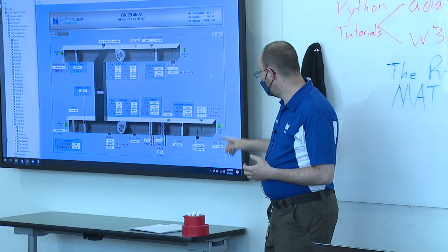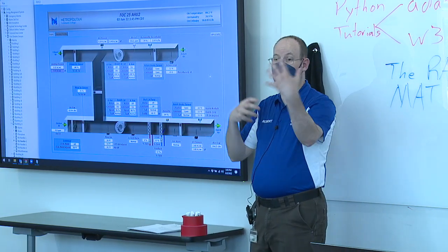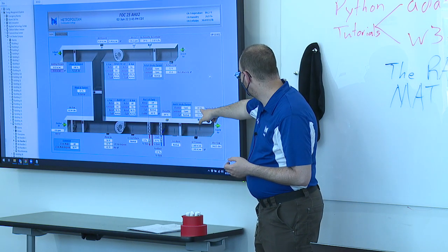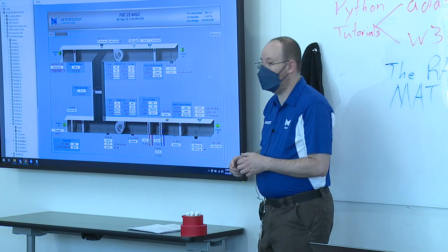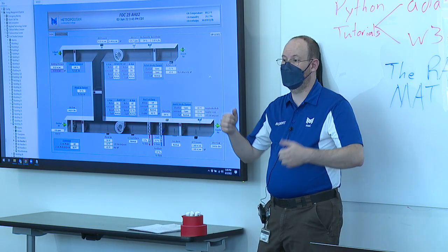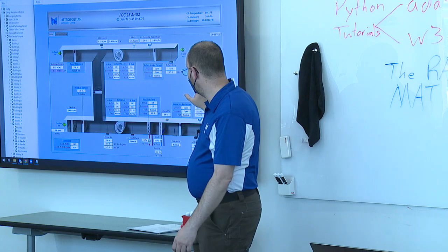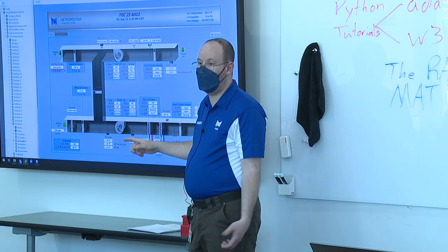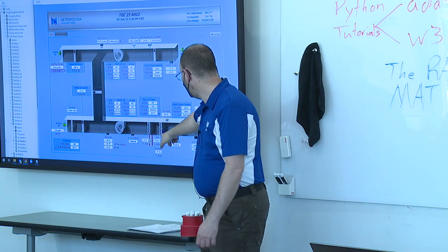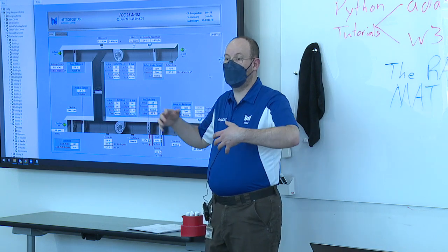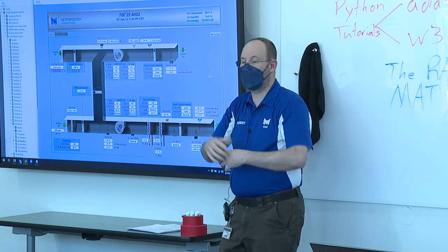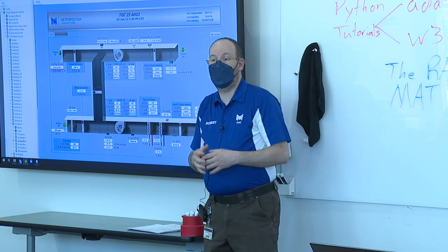Common features that we have is we're given information. We're given literal data. Our supply air temperature into this space is 49 degrees wet bulb, 55 degrees dry bulb, with a set point of 55, so we're doing good. We also commonly have some animations associated with graphics anymore. We have fans that spin, pumps that spin. We have coils that will glow brighter colors as the valve gets further open, dimmer colors as it closes, or completely flat when they're inactive.